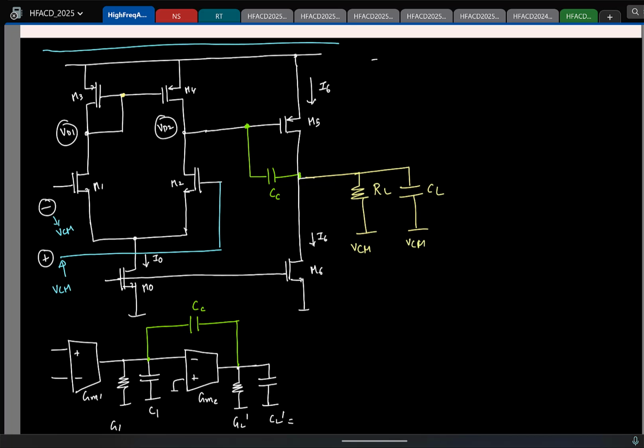Sir, if we change VCM, then we have to change the voltage there also. Yeah, the idea is, let us say for your op amp, you basically have the inputs here, negative, you will have a supply, you have a ground, and let us say you also have another pin for VCM. Typically this one VCM will be connected internally to all of them, right? So you just feed one VCM externally, and that will make sure everything changes.